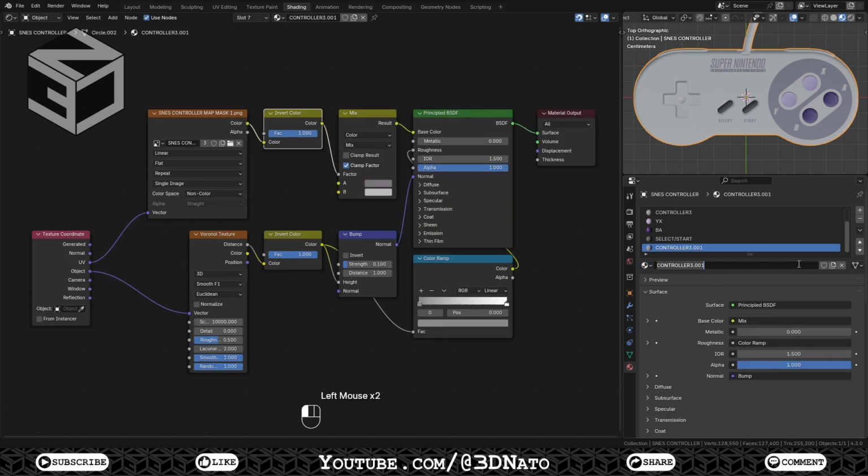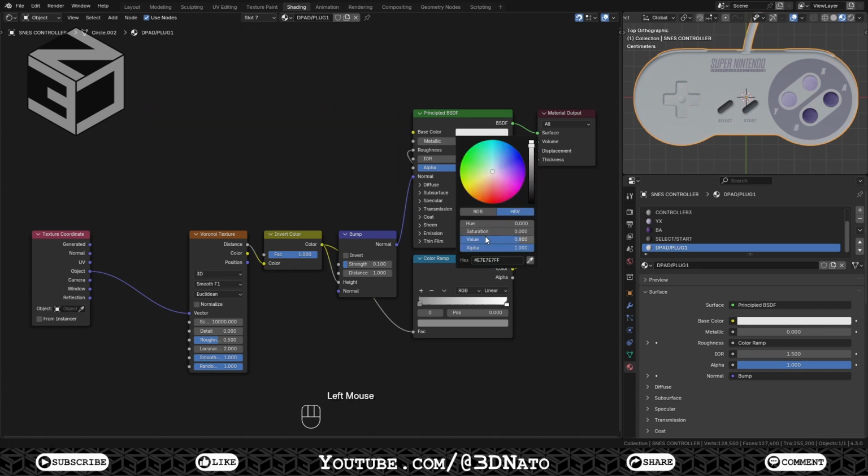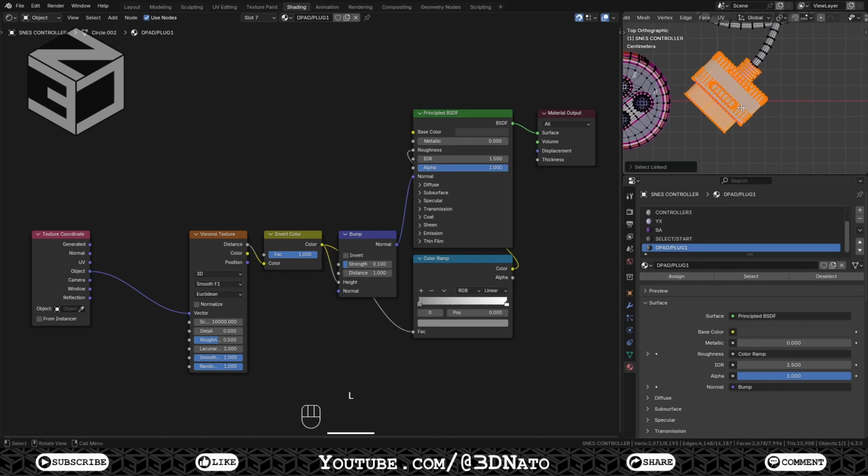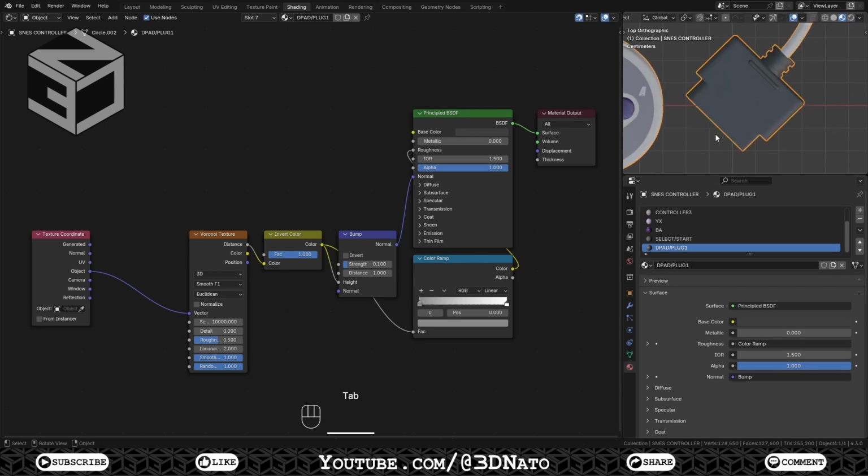Press the plus sign to add a new material, select the Controller 3 from the list, click this 2 to make it unique, and rename it D-Pad Plug 1. Delete all nodes going to the base color, and set HSV value to 0.05 to make a dark gray color. Go to Edit Mode, select both D-Pad and plug faces, click Assign, and exit Edit Mode.